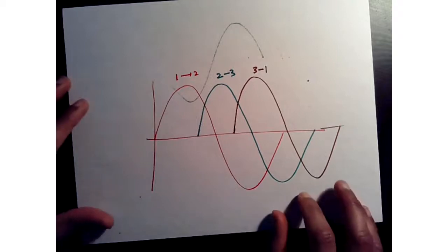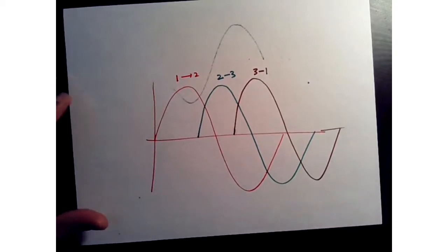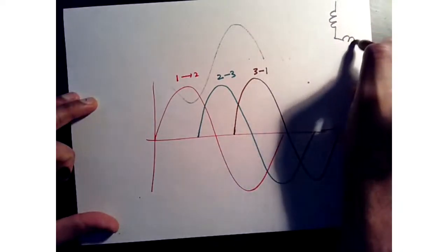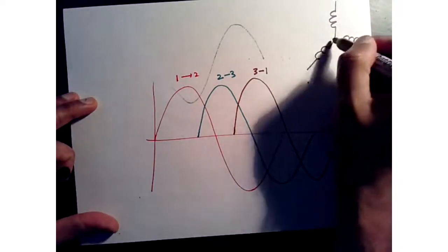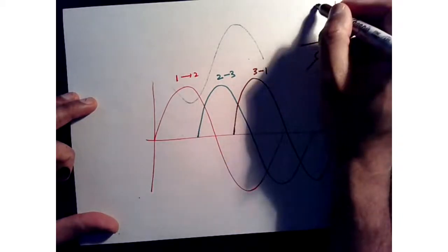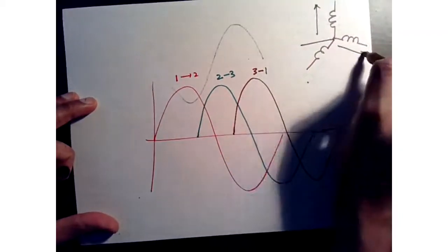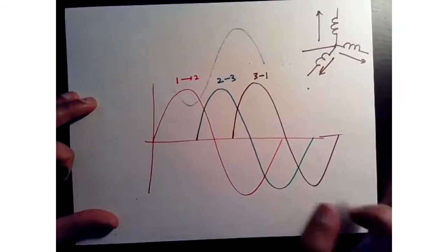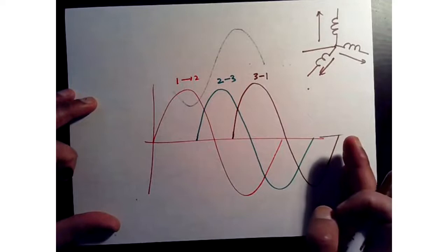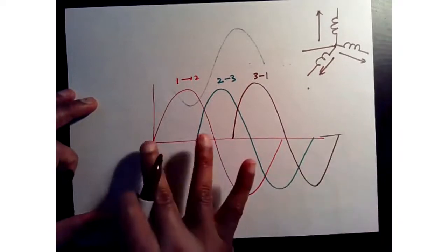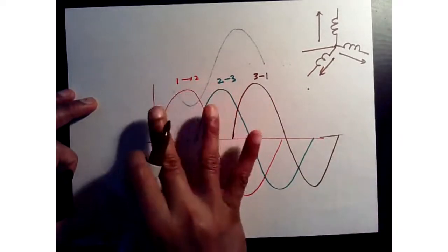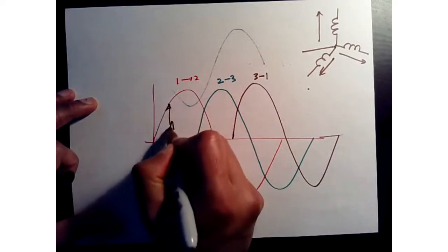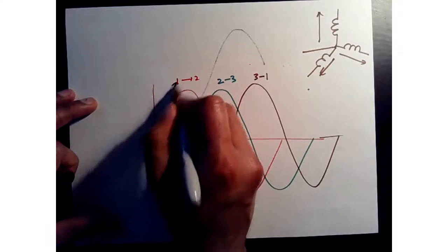If you have access to the neutral point, you can directly measure the voltage to the neutral point, or from the neutral point to a phase. So if you have access to this neutral, now you can measure these voltages independently and look at the phasing of them. Okay, so once you see these voltages, you can select 1 and 2. Okay, so you can name the first one A. Okay, that corresponds to 1.